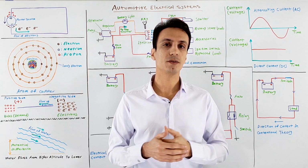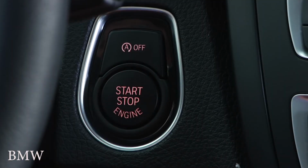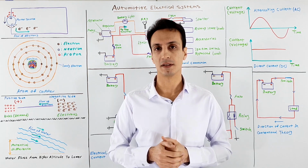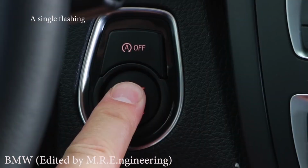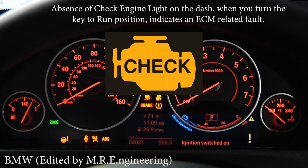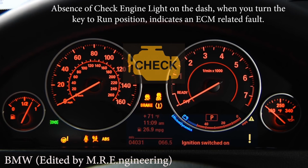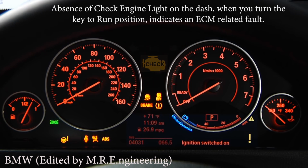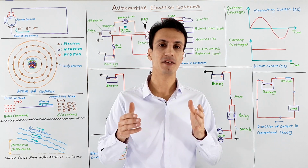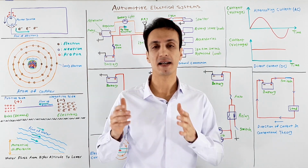Generally, when you want to start a car, always carefully watch the instrument panel when you turn the key to the on position. If no light on this panel is lit, probably you have a problem with the battery or its connections. But if you have some lights on this panel, but the check engine light is not lit, likely your ECM is the culprit. In all of these cases, you can't hear any noise from the fuel pump indicating that it's activated to get primed.